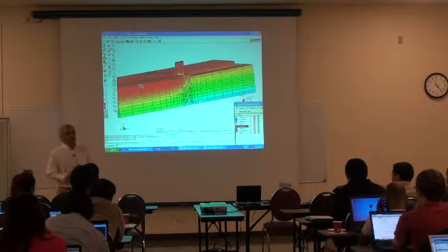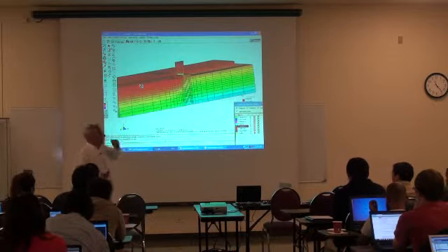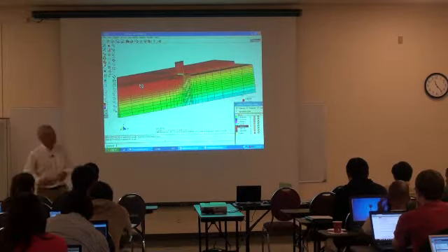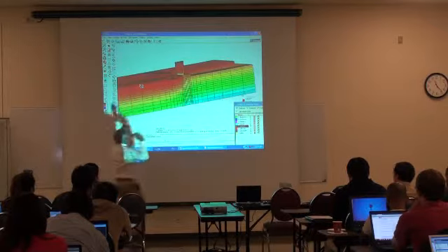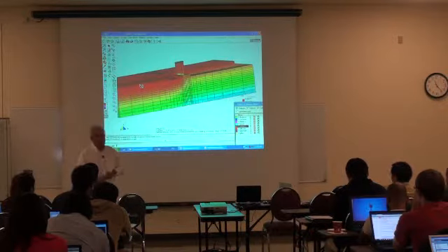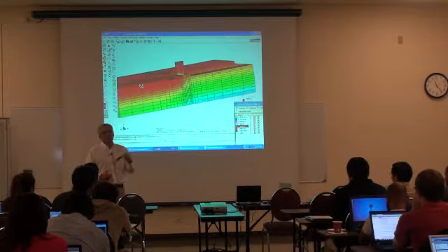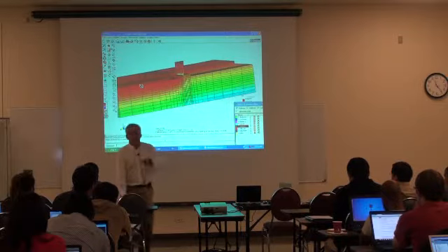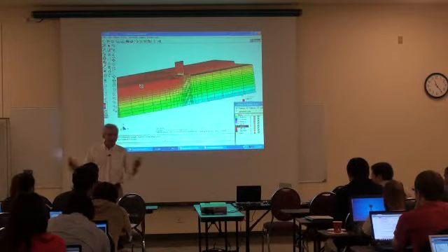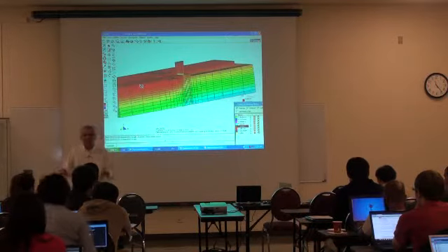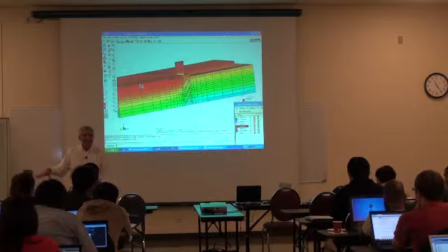What happens is that soils have permeability, and because they are permeable, the permeability stabilizes things. So I have seen a lot of people using the quad UP directly. Oh, the quad UP works well. Yes, because of the values of permeability that you're using, but it's very dangerous. I would prefer to use a stabilized one. It's simple, because your advisor will tell you, no, use the 9-4, and you will say, no, the quad is much simpler. I don't need to have 9 nodes and 4 pressure nodes. Who wants to go into that mess?